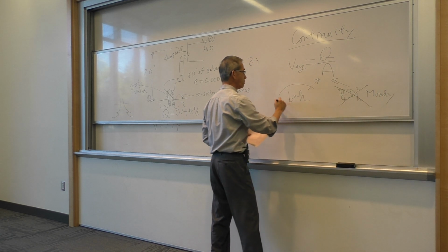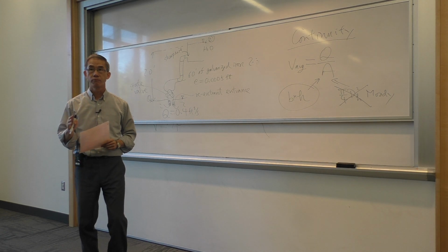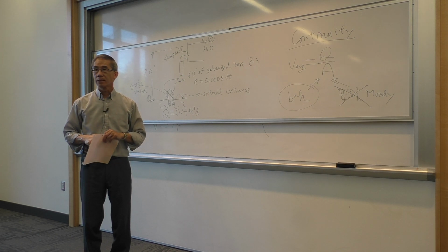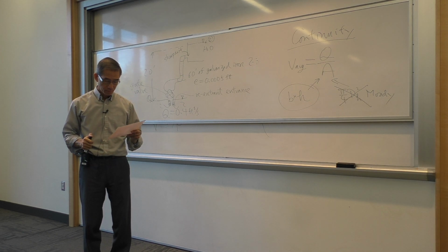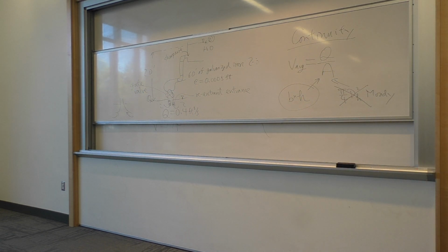The hydraulic diameter is purely for the use of the Moody diagram. So you don't need that for your homework. You will use the actual fluid cross-sectional area, because that's what the water or the air will see in getting the average velocity in the pipe. So I've given you all the information needed to do the next set of homework.